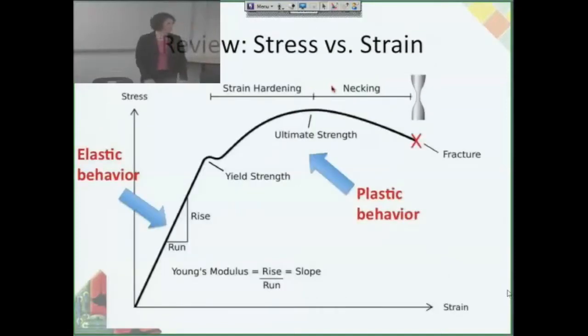This is a stress strain curve for a typical ductile metal. For low strain values, you probably have some elastic behavior, and you can take the slope of that in order to get the Young's modulus, which you can think of as stiffness. But at a certain point, it hits the yield point. That is the point after which it starts having plastic deformation, so it won't fully return to its original shape after you remove the force. It'll start necking if you're pulling it apart. If you're compressing, it's going to expand the other way, and then eventually it'll break.